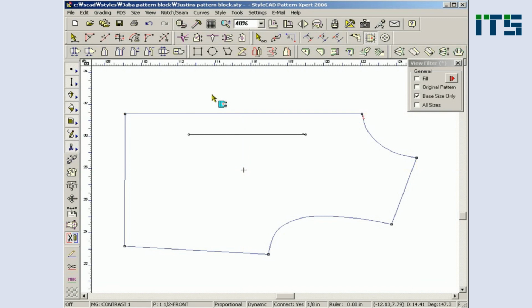Two-point guideline tool creates a guideline that goes through 2 points. Press the Ctrl key and left-click the ruler area. Then, drag from point A to point B to make a guideline connecting the 2 points. In order to move a guideline, select the guideline, enter the distance, and drag it.